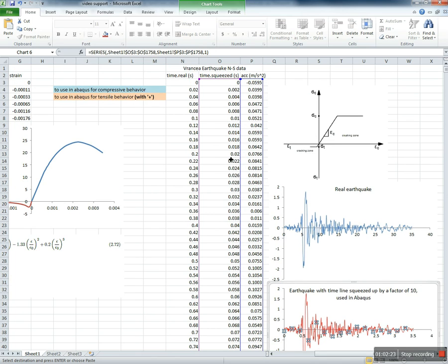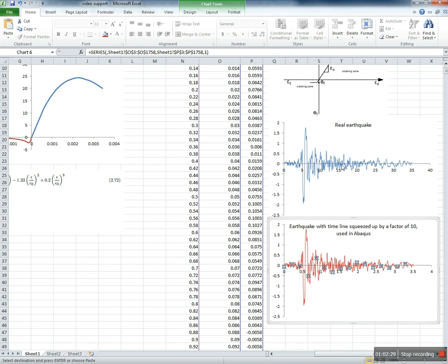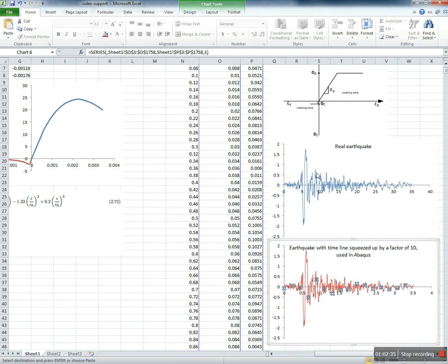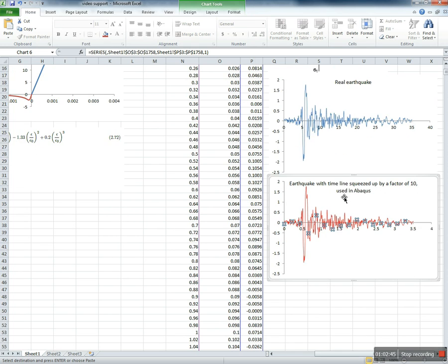So we will introduce this. You have 0.02, we will have 0.002 and so on, just to increase a bit the response of the structure. Maybe not, but you can just use any accelerogram and numbers that you want. This is just the working procedure, so you have an idea how to do it, then you know how to do it. You can use any structure and implement any accelerogram that you want. All right,